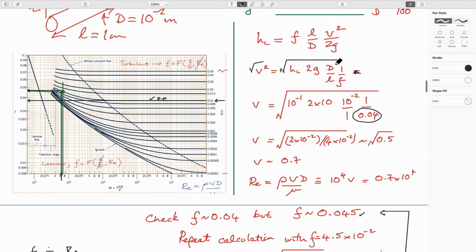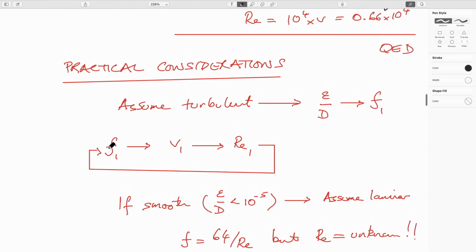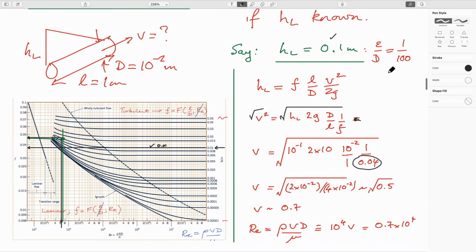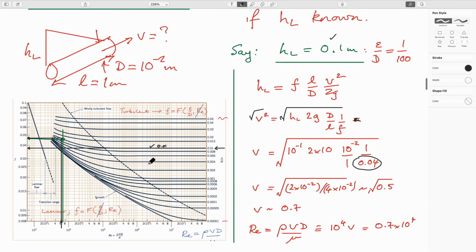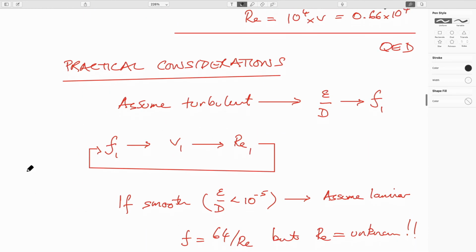We just chose an initial value of the friction factor based on the turbulent regime. It's just convenient for us to do that because we know we're on the flat part of this graph. If we end up being on the laminar side, it would work out okay for us as well. So in other words, just need to choose a number. If you know what the roughness of your pipe is, that makes it easy because then you can choose this. If you have a smooth pipe, then you just need to choose a number between 0.1 and 0.01, a factor of 10. It's quite constricted, and then do the same. And so, yeah, I'm making that point here.